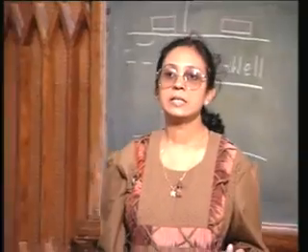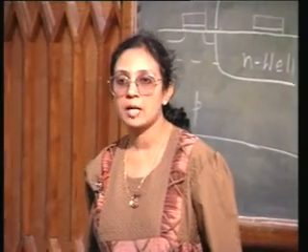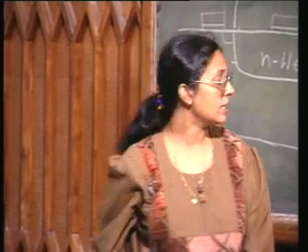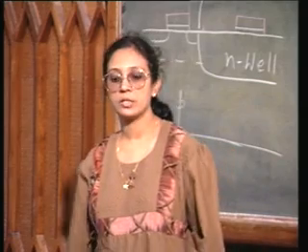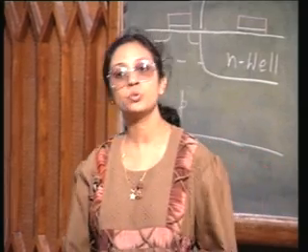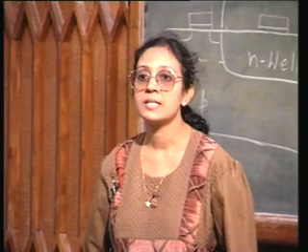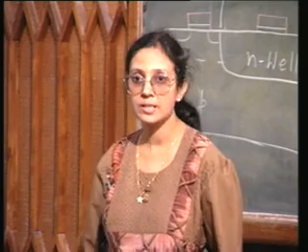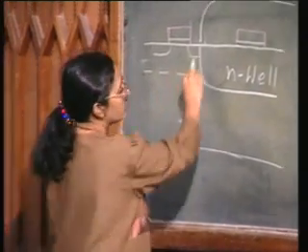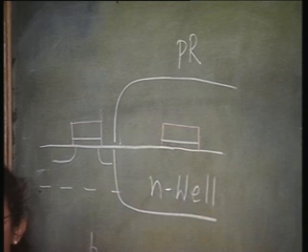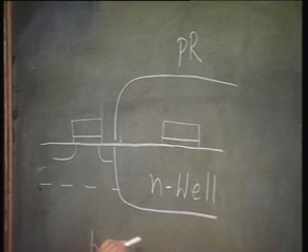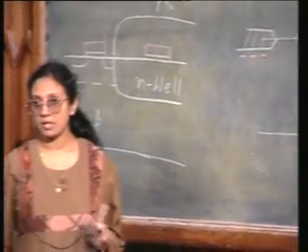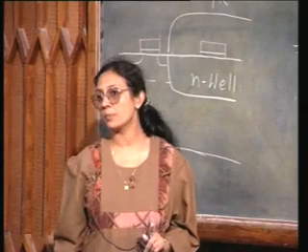So, you see this is actually the example of the secondary Twinwell. I told you that in Twinwell I can either have a true Twinwell or I can have a secondary well. This is essentially a secondary well, in which case I have started out with a p-type substrate and formed the Nwell, but there is one additional step involved.